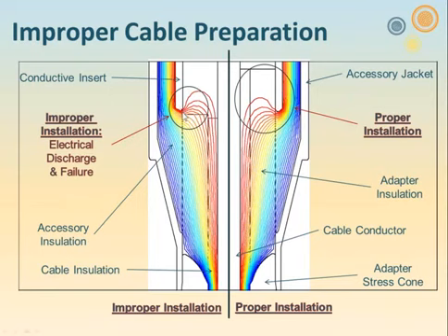If you look at the stress lines, the equal potential lines there, they don't look a lot different. Yeah, they're bending a little bit more up here. So what is the problem? Let's look at it a little deeper. This area right in here, we said we have 40 volts per mil along the interface. Perpendicular stress may be 50 volts per mil.